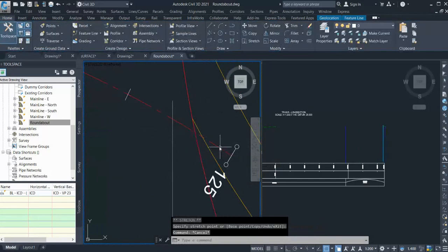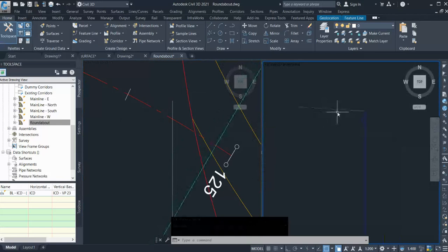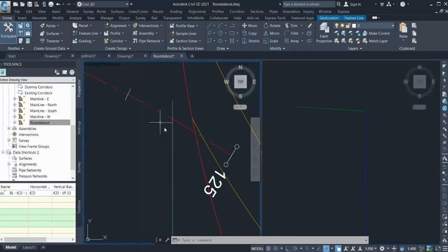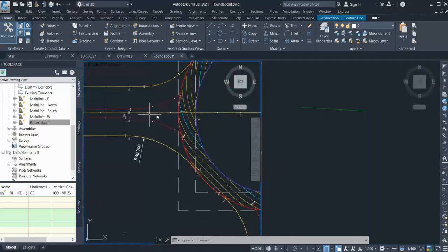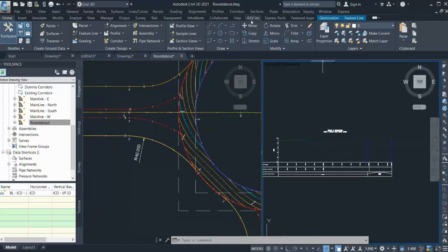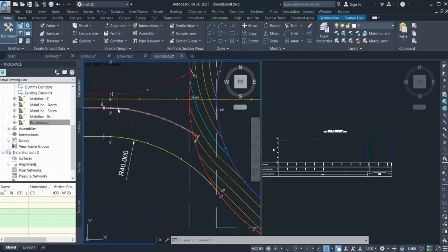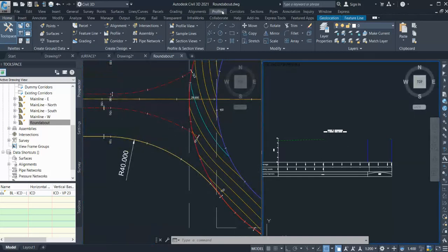You should always have some overlapping area. So here you can see if you have an overlapping area, you are getting the surface to tie in. So wherever you design those alignments, try to create some overlapping areas which could help you to tie in. This is just me dragging it. You shouldn't be just dragging like this. You should be dragging as per the curve. So this is just for the training purpose.